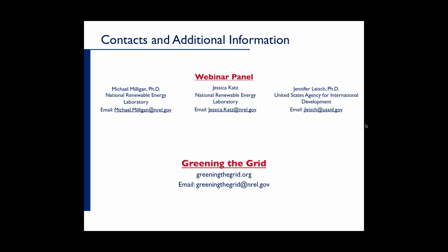Because many power plants need some notice before they're available to be used for energy, a forecast is helpful. And the way that you do the forecast will depend to some extent on how the system is operated. But a fairly typical case would be day ahead: the day before the time in question, the system operator has a demand forecast, and then gets all the generators ready to go, turn them on, and make sure that there's fuel and all of that so that they can be operated the next day.